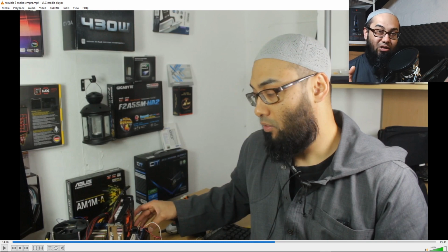So don't make assumptions. And I also said that if you do a swap of parts, you should keep everything the same, otherwise you would skew your results. And then after you confirm or you suspect that the motherboard isn't working, you should revert back to the original motherboard, just to make sure that one of your components did not die in the transfer. I hope that makes sense. If you guys understand, let me know.